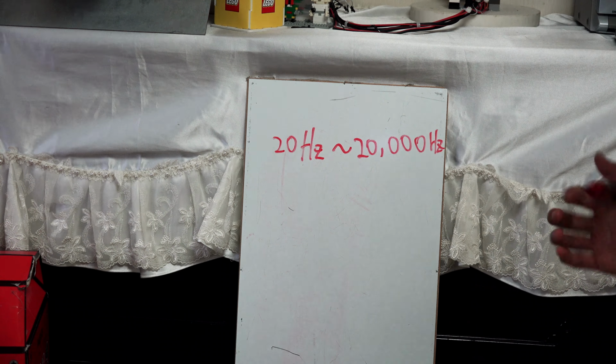And there is echo, and I will put it in digital 9. And lastly, there is a trigger which makes the sound of the ultrasonic sensor, and I will put it in number 8. And that's all we have to connect. So let's connect it to my laptop, and I will tell you how to write the program.